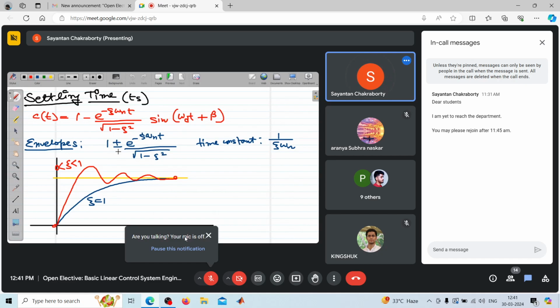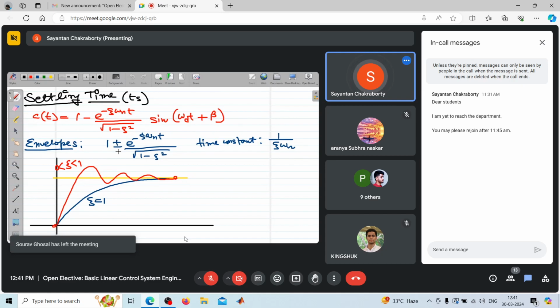First of all, the model that you're using is a simplified, in some situations oversimplified, linear time invariant model. Most of the systems that we encounter in nature are nonlinear. They are time varying. They're susceptible to parameter variation. They're susceptible to modeling uncertainty. They're susceptible to ignorance from our side because we are ignoring the higher order terms. We are approximating the plant to be second order, but it may contain third, fourth, fifth order. They may even contain zeros. We have considered the system to have only two poles and no zeros. So the effect of zero, we should study. What is the effect of zero?